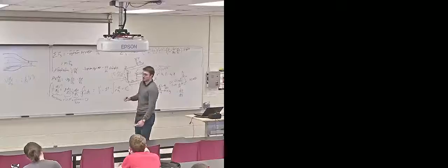which is going to lead us to, in this case, because everything is simply a derivative with respect to s, we're going to end up with v squared over 2 plus gz plus, this one's a little bit trickier, I'll get to this in a moment, 1 over rho dp ds is equal to, sorry, not 0, the indefinite integral of 0 is a constant, right? So why did I leave this one inside the integral? 1 over rho dp ds.